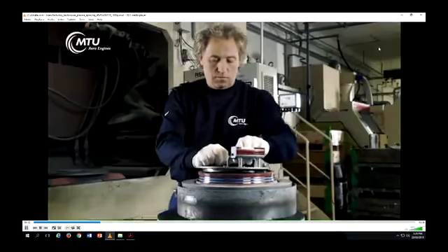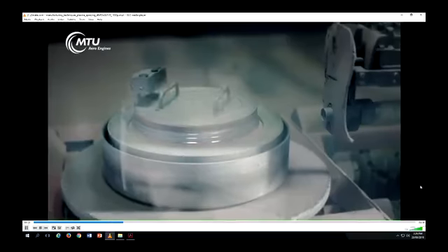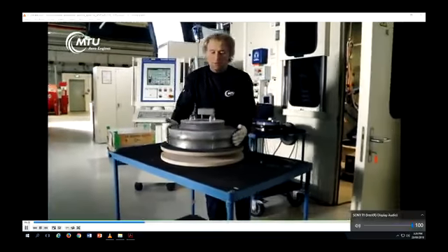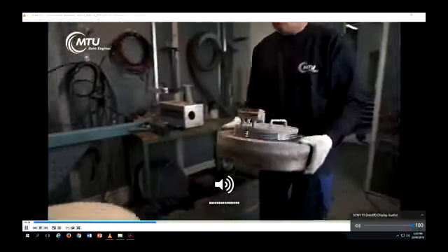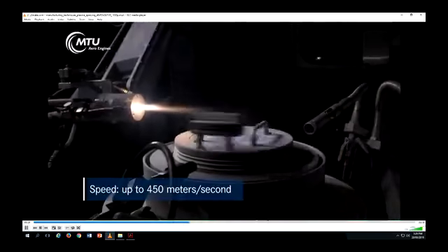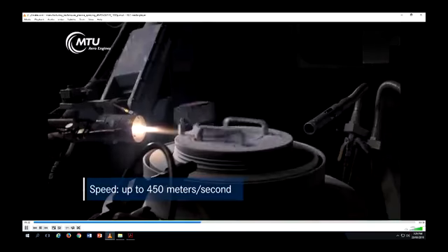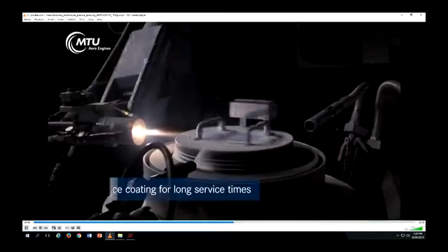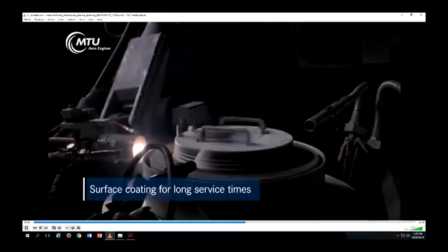Thermal spraying process is plasma spraying. Masking defines the areas to be coated, so that the particles to be applied adhere to the component. It is cleaned first. In this surface coating method, powder particles are injected into hot plasma and thereby melted and hit the surface of the component at speeds of up to 450 meters per second. There, they form a material layer that fulfills the requisite characteristics for its function, for example, as wear protection.